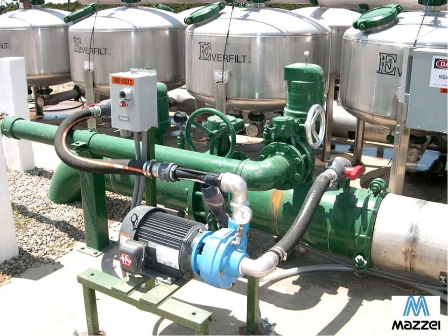And this is a typical booster pump application where you have a pretty good flow, probably 800 gallons per minute in this system, and they are using a 2-inch injector which has the capacity of pulling in 10 gallons a minute. And that's the setup.